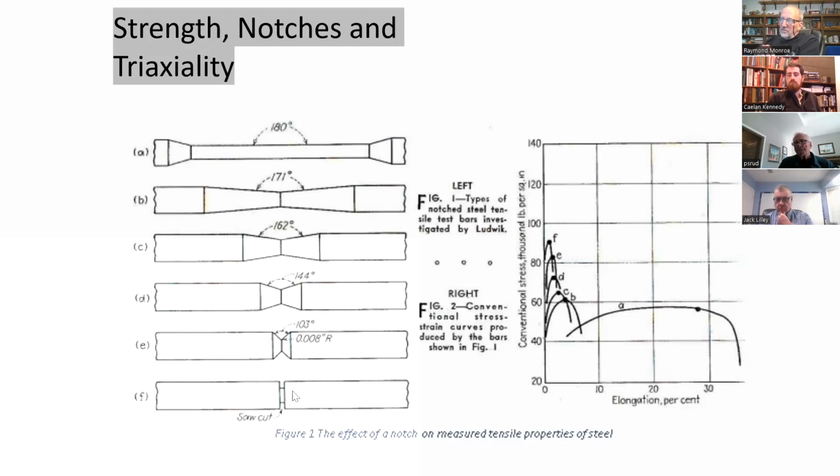One of the ways I've always explained this is to say, the problem here is you can't satisfy Poisson's ratio, and you can't find a favorable failure path in shear. So I can't find a shear path to fail on, and I have to put a lot more energy in to begin dislocation and failure because I can't satisfy Poisson's ratio. I may want to start to pull apart, but to pull apart, I have to get smaller, and I can't get smaller.